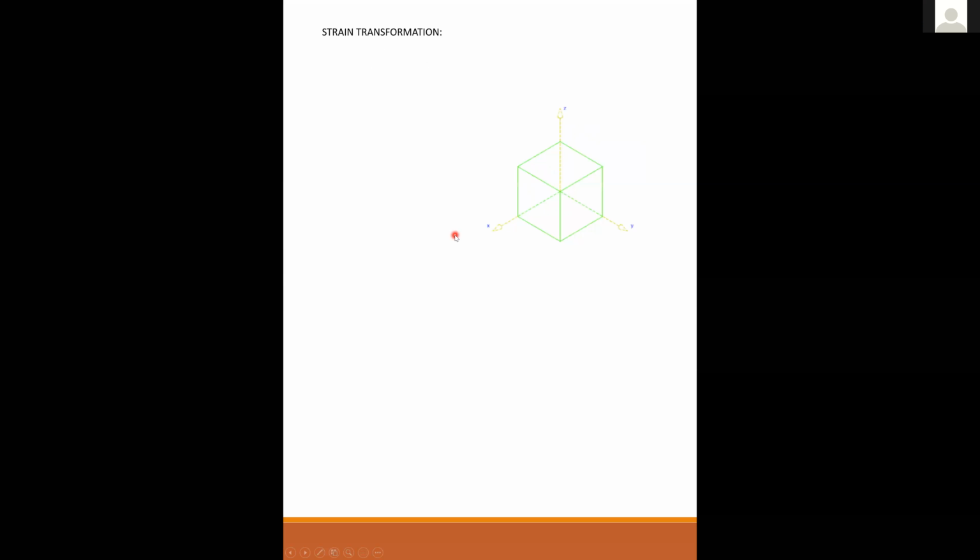So just a clarification, Professor. So the circle is a little bit tilted with respect to the tau and the sigma axes? Yes. It's not symmetrical. And also it depends on where A is, right? If A was more off to the right, then the minus 90 and positive 90 would be more off to the left. Yeah, the whole circle is skewed over by the average of sigma x plus sigma y. Okay, that makes sense.